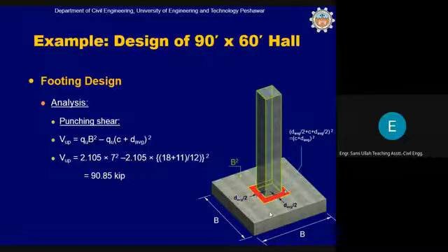This part will be going into the foundation along with the column. If I show you an animation, it will look like this. So the hole will be made at this perimeter, and the remaining area will be considered in the calculation of this punching shear.